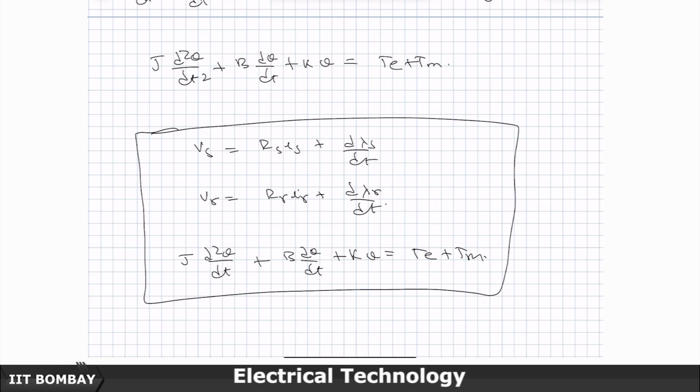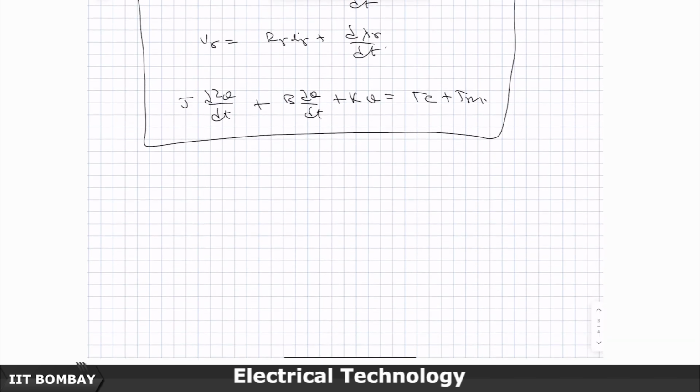So, it becomes constant at I sine of theta. In other words, in the study of synchronous and induction machines, we are interested only in sinusoidal steady state. Therefore, we proceed to find conditions for average power transfer in that steady state condition.